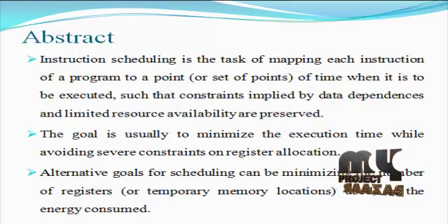Clusters are the main computing part and the two most power-consuming and hot components in stream processors, such as Imagine, Storm and AMD, and functional units, which are controlled by very long instruction words. In most stream processors with VLIW architecture, operations can be executed simultaneously on multiple functional units to exploit instruction level parallelism. Unfortunately, the large number of functional units and increased operations per VLIW bring severe energy increase and thermal problems for stream processors.